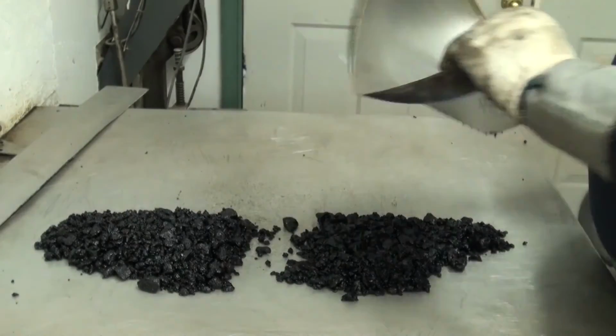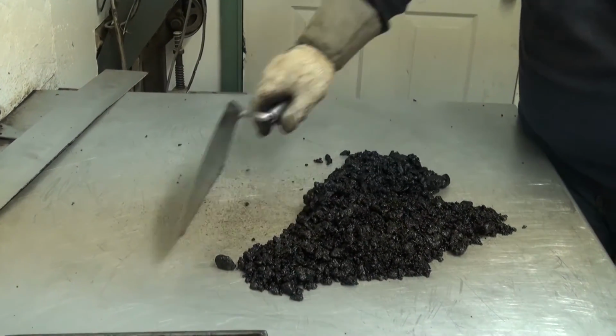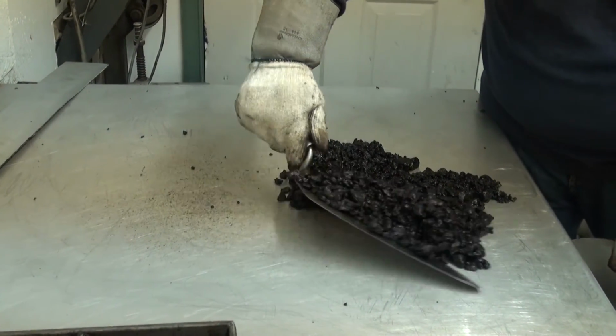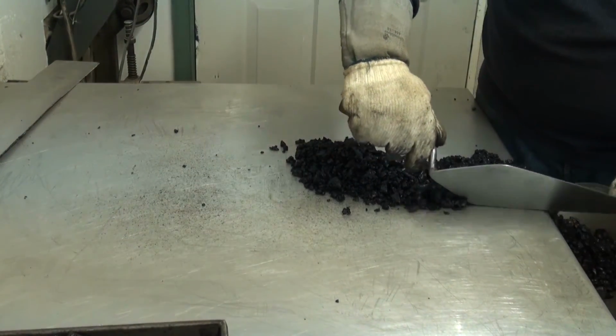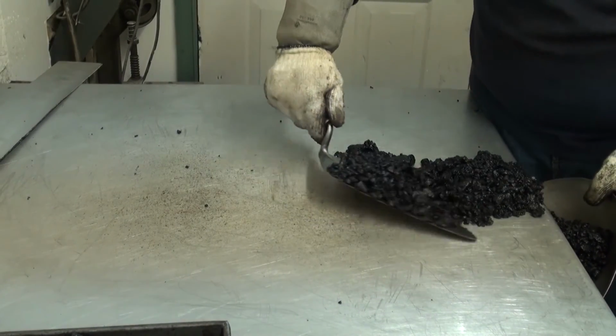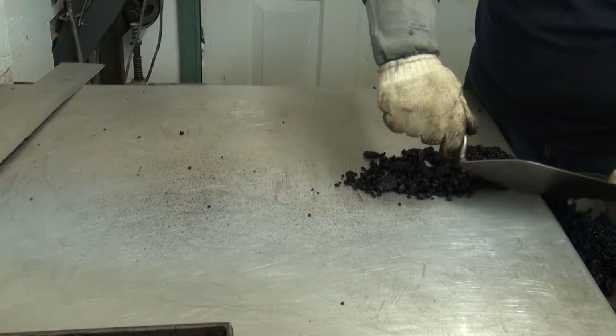I hope you noticed that we did not use any scooping during any of this process as he attained his sample size. Everything was done by quartering. Now he's taking the other two quarters that have been combined and he's putting them in a weigh scoop here. Probably a good chance this is going to be a furnace burn and a gradation sample.